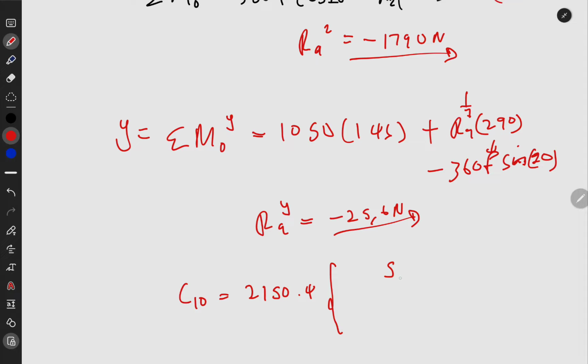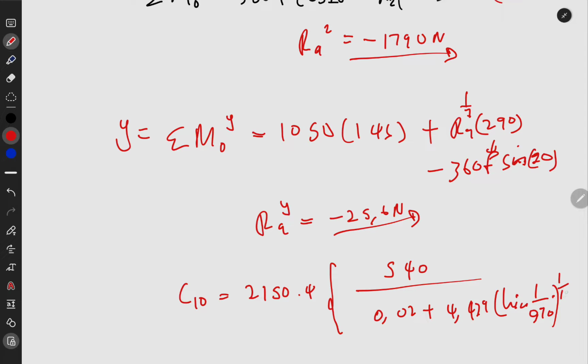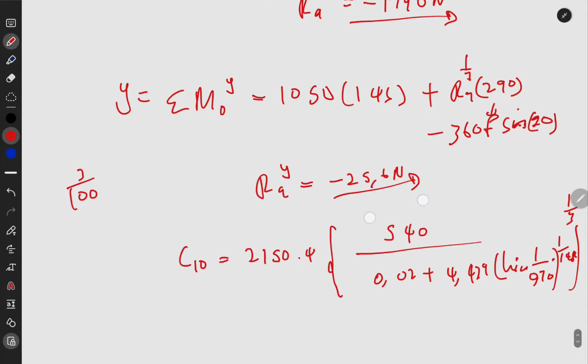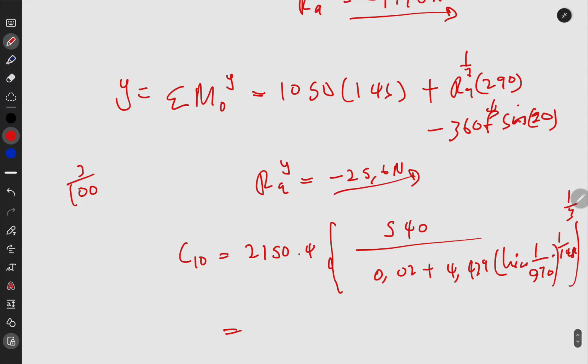So we are literally going to do a lot of substitution. Until now it's just you with your data sheets and the tables, and then you substitute everything, and I think the hard part of the problem is already conquered. You could just finish up from here. So it's just data now. That is 1/3. You know that if it was a roller, you'd have used 3 over 10 here on the exponent. So that's literally your data sheet for formulas, nothing much.